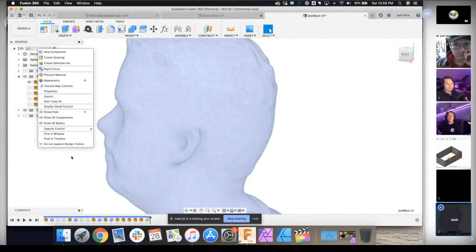Okay. So you can input everybody else's STL. The faces, if it's a flat face, it'll get broken up into really weird triangles. So it's not the best at doing it. I usually use Mesh Mixer to alter an existing STL. But Fusion can. It just gets kind of fickle.